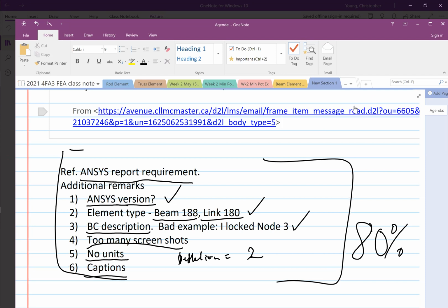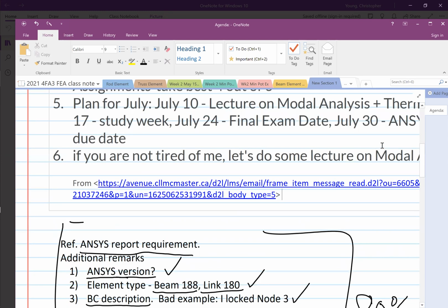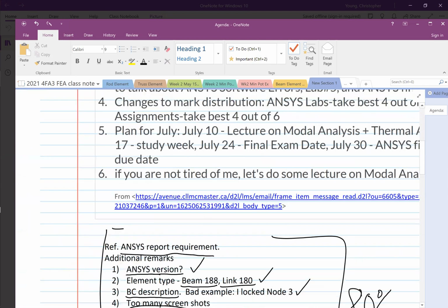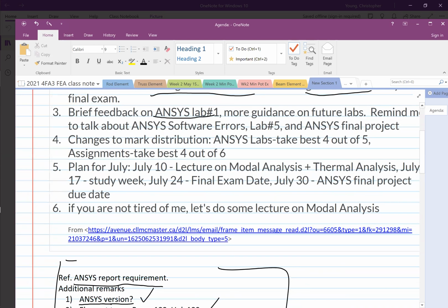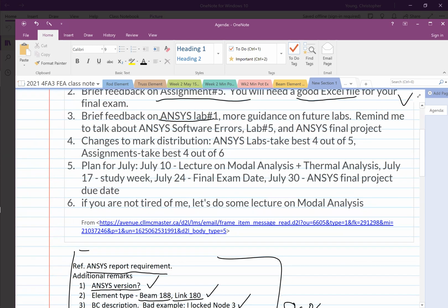Yes, yes. I think you just play around with plot control. Under plot control, you have many things, just try each one, don't be scared. Like the deformation shape or the deform shape. Yeah, that's right, I think he can go back. If he wants to show the deform shape, and then if he wants to show the nodal solution, that's fine. Yep.